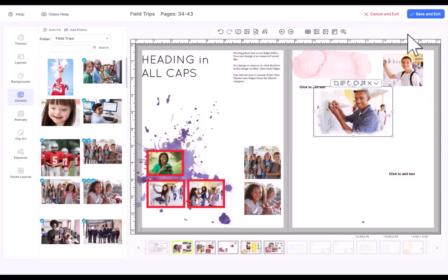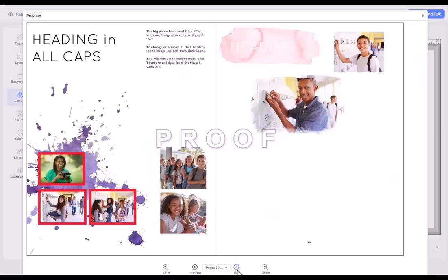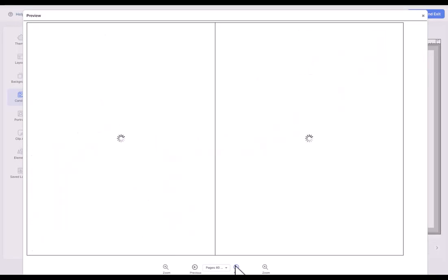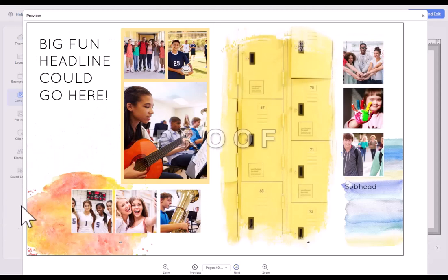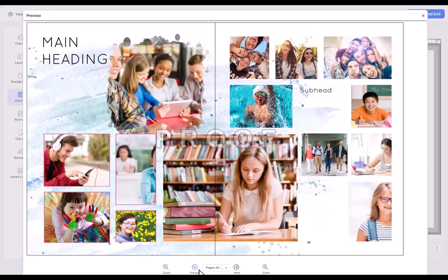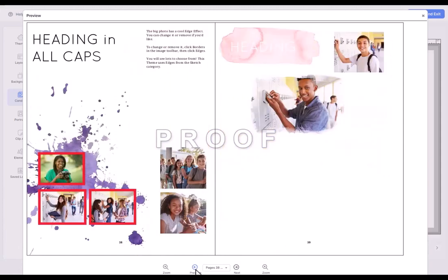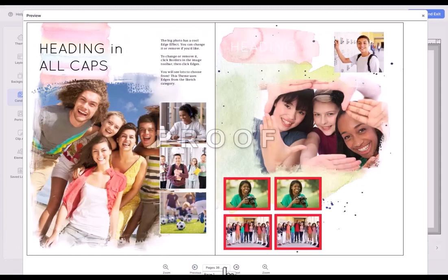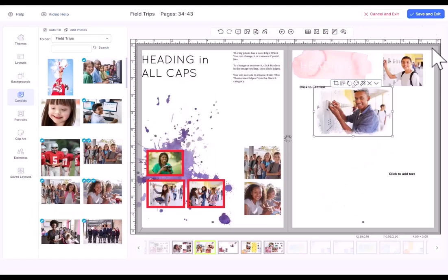The last thing we're going to look at here is the preview. The last icon here up at the top gives you a preview of your current section. Something that's important about this preview is it actually takes off the dark gray trim. And so this preview is more accurate with respect to what you'll see on the printed page. If you're worried about something potentially being cut off, if it's cut off in the preview, you're probably going to want to adjust it. Okay, again, with the preview, you can navigate through by page numbers and so forth, and you click X to close it out.